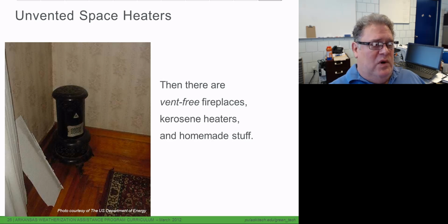Unvented space heaters. Oh boy. Unvented space heaters are a real problem because while they're vent-free, they are not poison-free. Now this is for combustion appliances, is what I'm talking about. An electric one, yeah, that's going to be poison-free for the most part. It has its own safety issues. But aside from the safety issue of having an open combustion source inside the house, the biggest problem that you run into is moisture. Moisture is a byproduct. Remember I told you you get two things from combustion, carbon dioxide and water, along with heat.